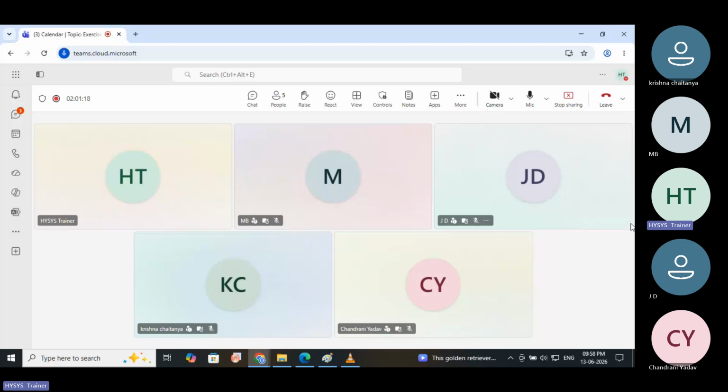Then in the last part, we saw how we can change the color combinations of different streams based on temperature ranges. We saw this for temperature ranges as well as pressure ranges. Like that, you can change the stream colors based on any particular parameter which is selected, and you can allot the ranges for that particular color of the line and change it accordingly. Then we saw the column environment, how we can check the details inside the column by going into the column environment, and we can return by simply clicking on the go to parent button. So this was all about today's session on the acid gas treatment plant.